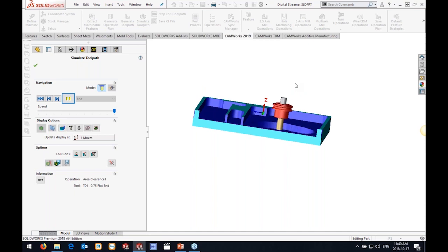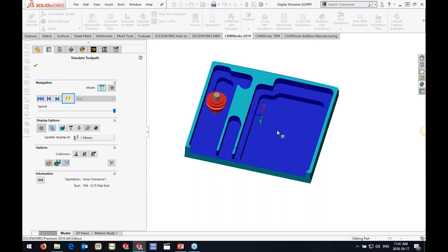and then it will machine up to basically a point where it will holder check, and now you'll see it's not going anywhere near the walls there because my holder would hit in that region, but it's fine in the middle, so it goes and roughs all that material out. So that's a great new option for doing this type of work where you may have short tools just to increase stiffness, but you want to go in with a volume mill style toolpath. So now you can go in and check the holders.